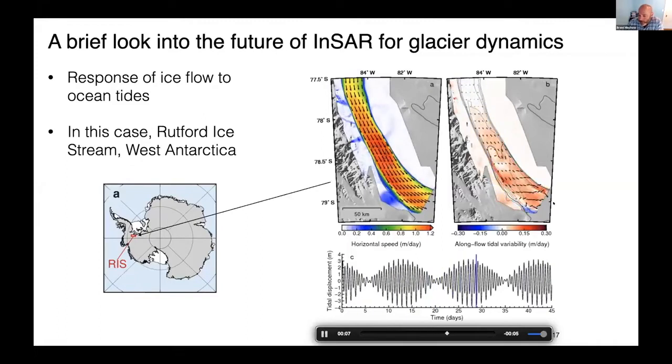So this is the result of that. What we're showing here is a total velocity field and how it changes in time. And on the right-hand side is variations in the velocity, all done with offset fields that Brian's going to talk about later. What we're showing along the bottom is a simple tidal model that just gives you a sense of where we are in the tidal cycle. You'll see this general beat cycle, this low frequency cycle here. This is the spring-neap tides. It all has to do with the alignment of the Earth, Moon, and the Sun. And it basically comes down to a period of half the period of the moon, so 14.77 days or so. That's the primary variability of the horizontal flow in Rutherford. So what we think is happening here is that the ice shelf is going up and down.